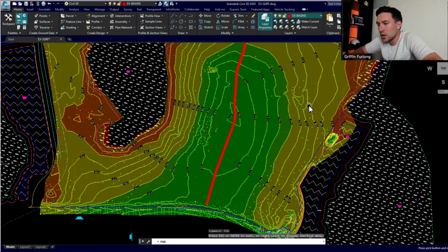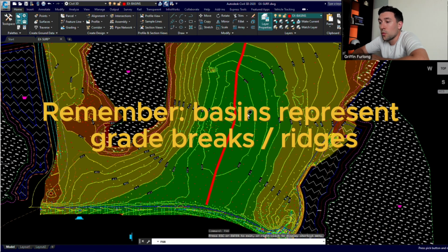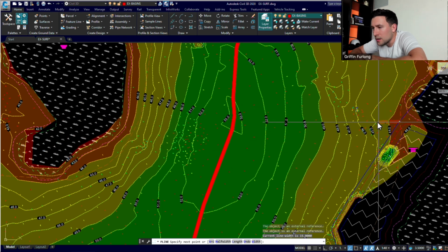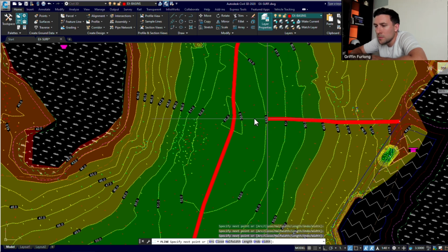So if I'm looking at it here, if I'm a water droplet and my hand's right here and travels perpendicular down this course, this water droplet makes its way basically right here to this wetland and doesn't go into this pond. So I'm trying to develop the best approximation for this basin line. But I think a line right here is pretty dang close. So again, I'm going to be going perpendicular. I'll do my best to go perpendicular. And then I'm going to go up to this range point.